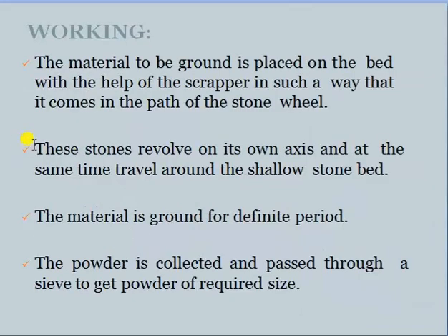The stone revolves on its own axis and at the same time travels around the shallow stone bed. The material is ground for a defined period. The powder is collected and passed through a sieve to get a powder of the required size.